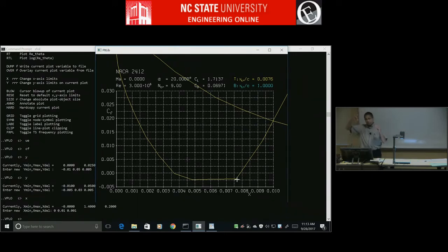So as the flow goes around the leading edge, it starts on the lower surface stagnation point and goes around, right? It gets its laminar flow, but then it gets this massive adverse pressure gradient. And we all know that adverse pressure gradient will either transition the laminar boundary layer to turbulent, or it will separate it. In this case, it separates it, but very quickly the separated laminar boundary layer or separated laminar shear layer becomes a turbulent shear layer, which very quickly reattaches. So it's such a tiny bubble that it's there, but almost invisible.